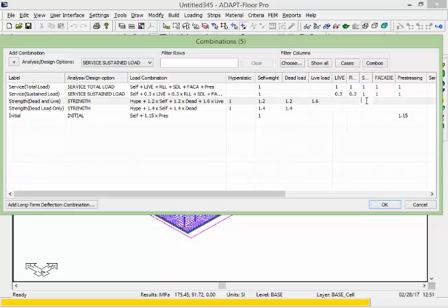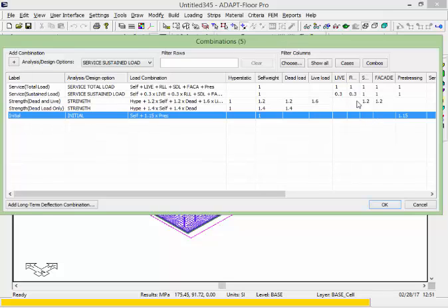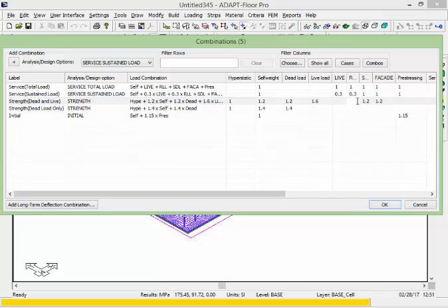And here we'll use 1.2. I'm essentially using the same factors for the new load cases. Delete that and that. And then this will include only 1.4 times the superimposed dead load, 1.4 times the facade load. So we have self-weight also for that individual mat at the base.